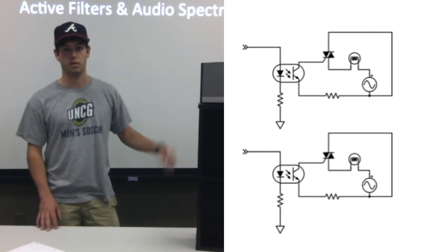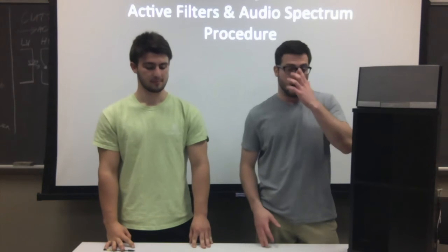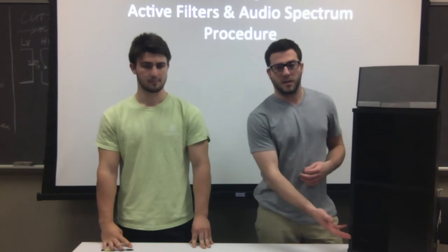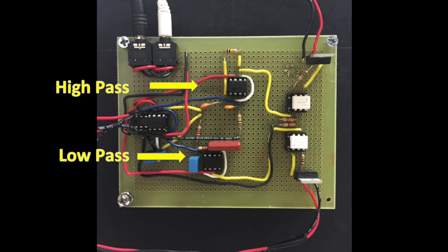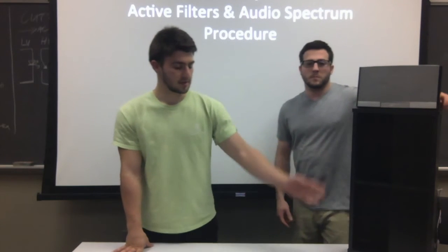circuit to interact. The first step of this lab was to construct the 2 filters, the low pass filter and the high pass filter. The high pass filter to turn on the one light and the low to turn on the other light. We first did this by scaling the low pass to 200 Hz and the high pass to 1000 Hz. The next step was to build both lighting circuits.